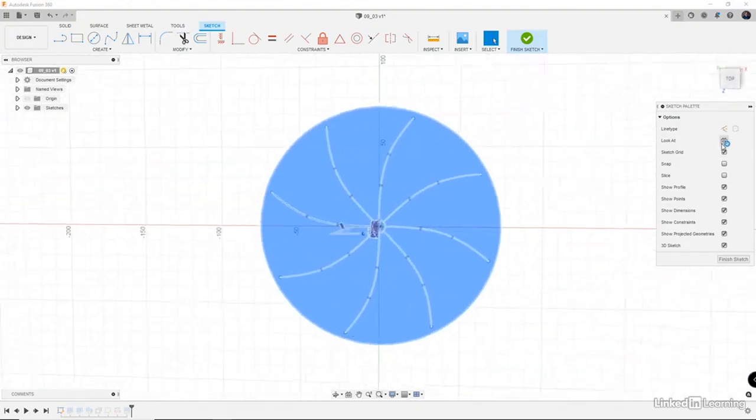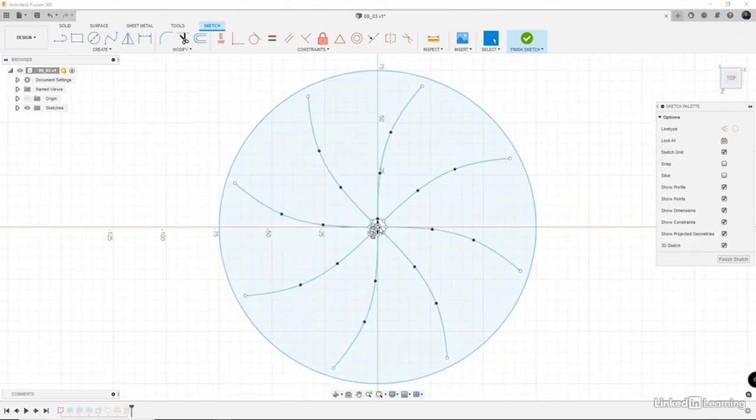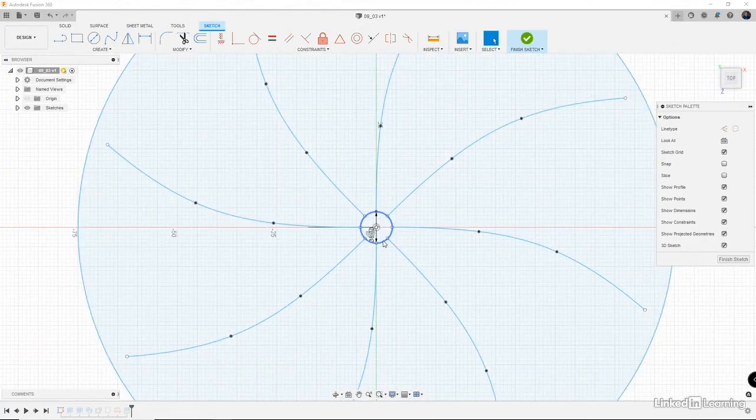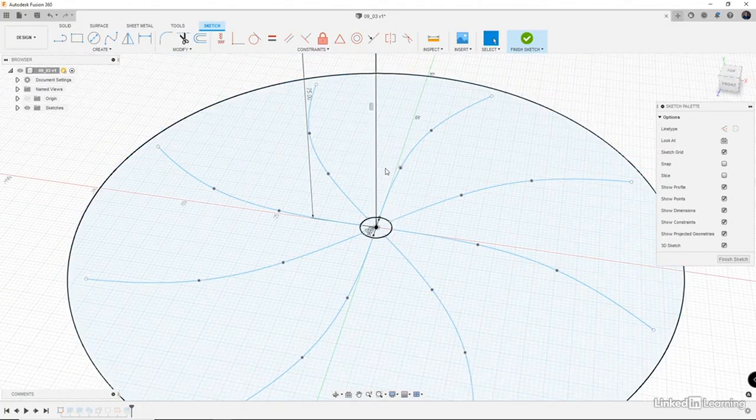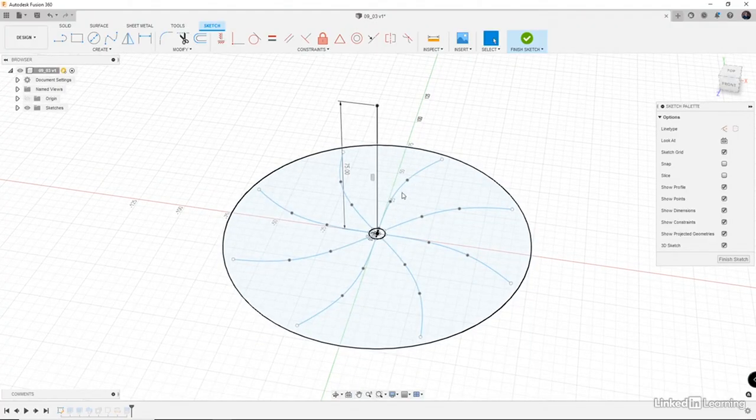It's basically a circle with a spline that was pattern generated around this circle, then another circle inside of it that trimmed it, and then a 3D line that goes right up the center. That's essentially what builds all this geometry. Obviously, this is updatable, so if we made modifications to this, we could change the dimensions of our part. So that's something to keep in mind, that this is completely updatable.